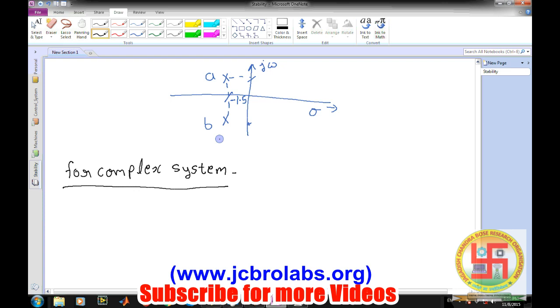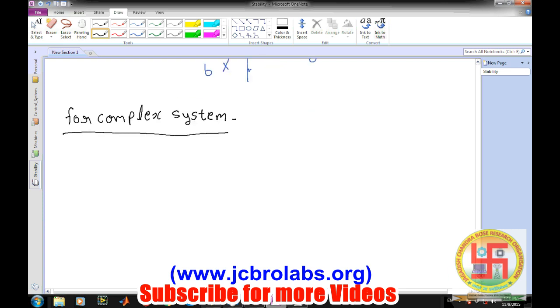We are not interested in the exact value of those roots. If somehow we can identify whether there are no roots, or one root or two roots, on the right side of the S-plane, then without finding the exact location or values of these roots, we can say whether our system is stable or not.